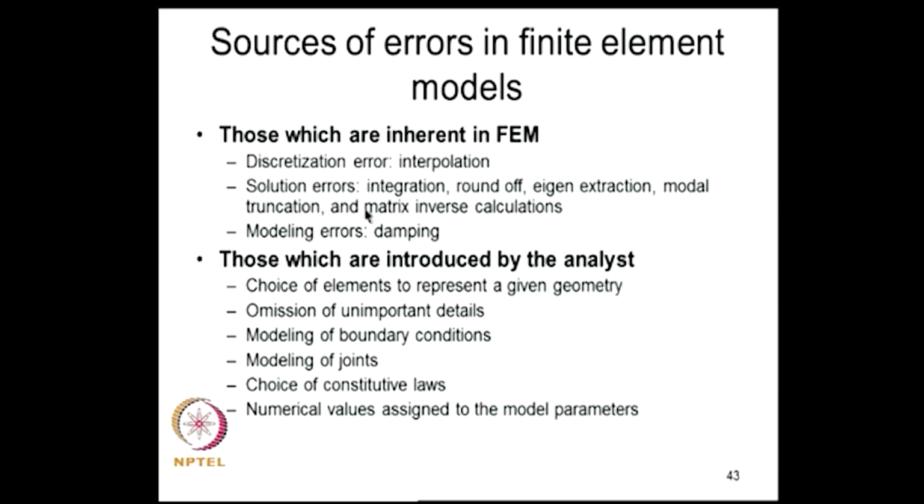Then there are solution errors. You carry out integrations, there is round off on a computer, you will adopt certain algorithms for eigenvalue extraction, you expand the response in mode shapes, and you may truncate the modes at a given value, and there are many computational issues like inverting matrices and so on and so forth. The other issue is modeling of damping. So, damping is a very contentious issue, whether damping is linear or non-linear, viscous or structural, proportional or non-proportional, or a mixture of all of them. There are many issues there.